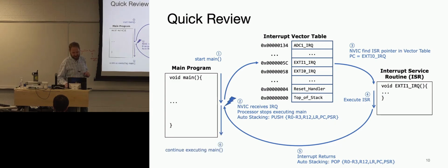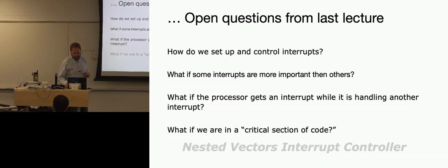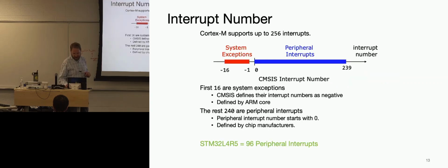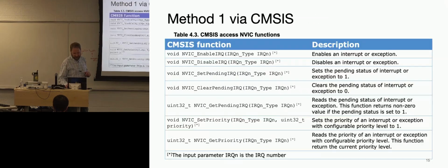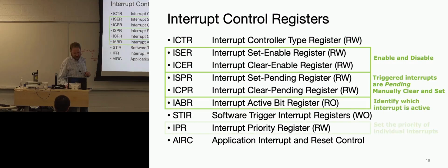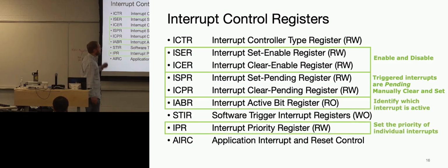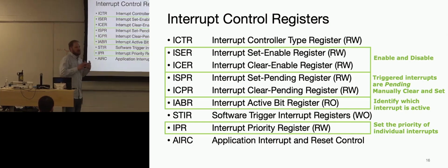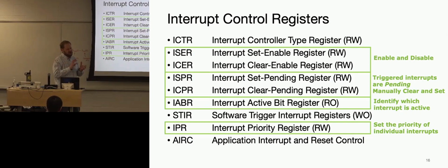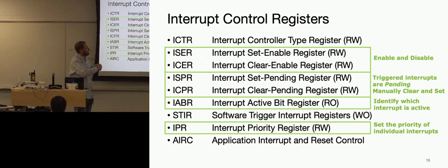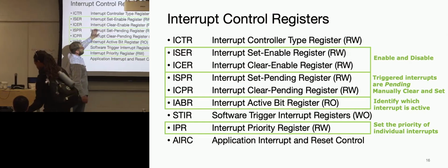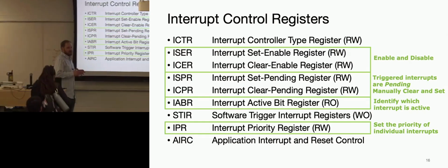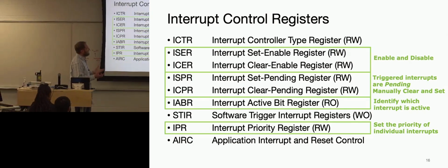No questions. Okay. So we blasted through some of these slides before, but I wanted just to highlight the ones that are particularly important, and we'll go through some examples. So we have the interrupt enable. These are a bunch of registers where you're not necessarily configuring the interrupts; configuring some of the ins and outs of the register is done in the peripheral. But in the NVIC, you're going to write in and say, I want this thing enabled, or I want to clear it.